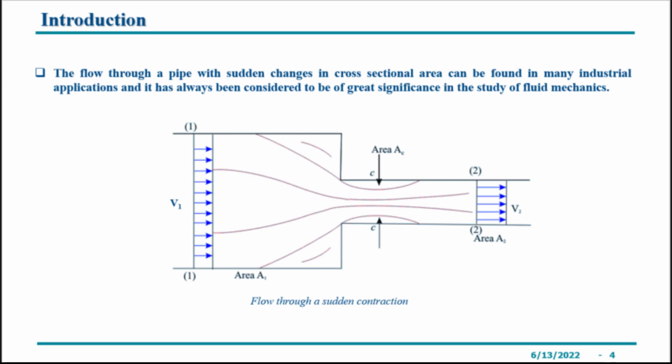In the beginning, let me give you a very short brief about this problem. As we said, the flow goes through a pipe with a sudden change in cross section from large to smaller. The velocity of flow in the converging part from section 1 to section 2 of Vena contracta is increased due to continuity, and pressure decreases in the direction of flow in compliance with Bernoulli's theorem.